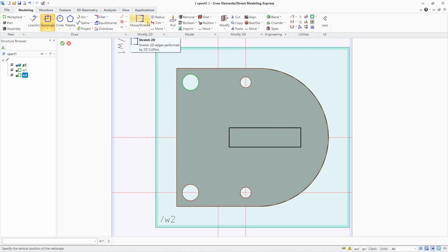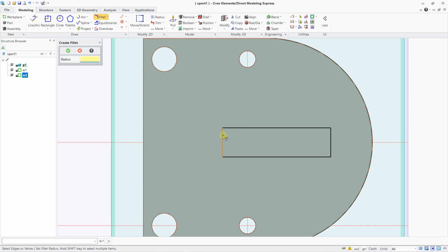And you have also different types of options. If you want to add a fillet, you can click on fillet, and I can click here on this one and this one, and I can apply a fillet like 2. Radius is not specified. Let's apply a fillet from this one to this one, and just drag and move with 2, and just validate. I can click here, select again my fillet tool, click here and click here. And let's work with a value of 2.